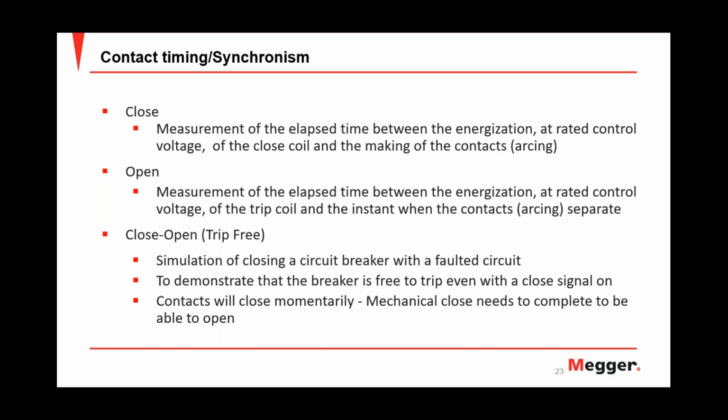Some automated test sequences are performed by circuit breaker analyzers to simulate conditions like closing a circuit breaker into a faulted circuit, when a close-open operation is tested. This is to demonstrate that the breaker is free to trip even with a close signal on.